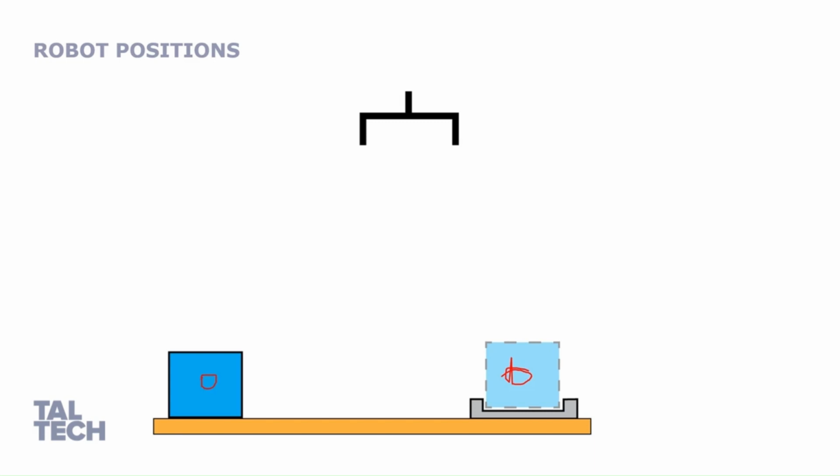Why are they exact? Because we know where the objects are located or where the placeholders are, and we can very easily teach them correctly. However, we are not able to go directly by the gripper to the box itself to pick it up. So we need an upper position here, which allows us to move safely to the box itself and grip it.